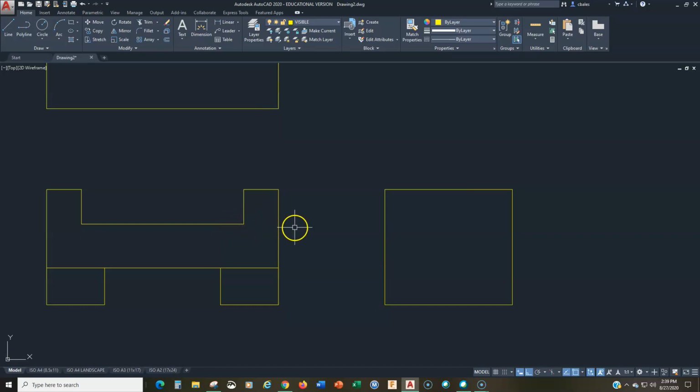Now, I can project these lines across. So this is the same as we would do in sketching, just a little bit different with AutoCAD. I can go to the line command and watch. Again, this is a very good technique. I can move over and acquire that point. I'm not clicking, and I'm going to track across, and then it's going to, boom, find that intersection, and then I can click and, whoops, I don't want to get the midpoint there.